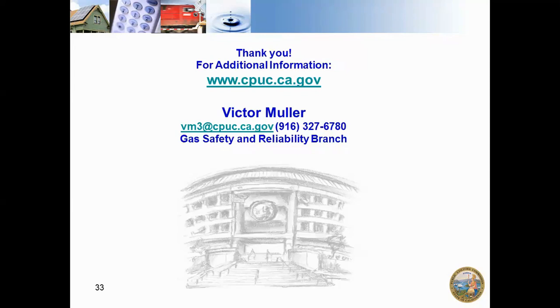So abandoned means a very specific thing under Part 192. There's really only two statuses that a gas line can take. One is active and the other is abandoned. So in an abandoned facility, there's requirements in 192 as to what that entails. And abandoned facilities are blown down.